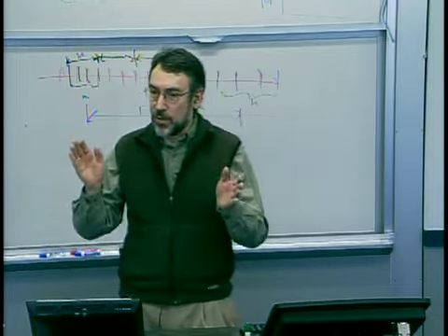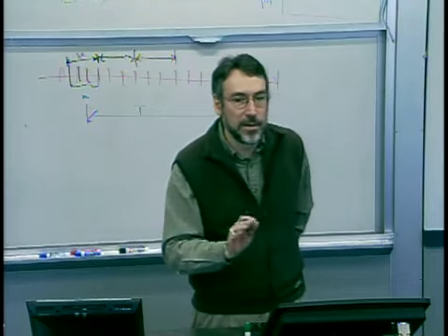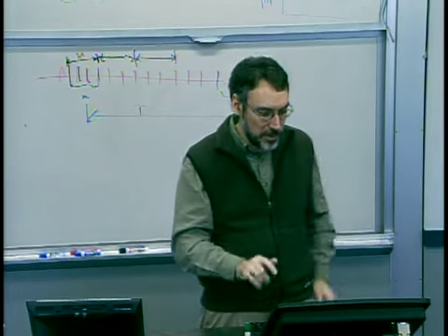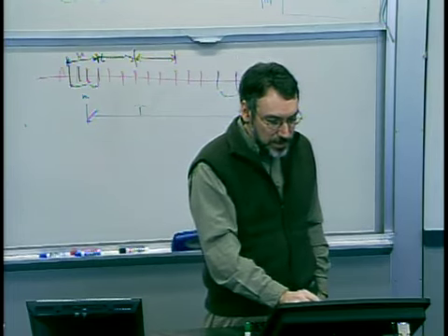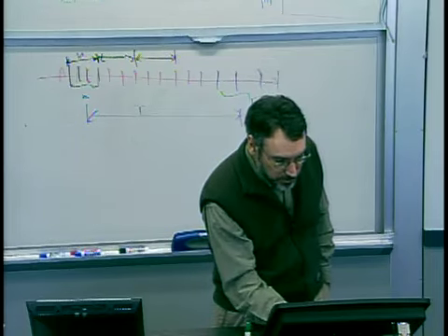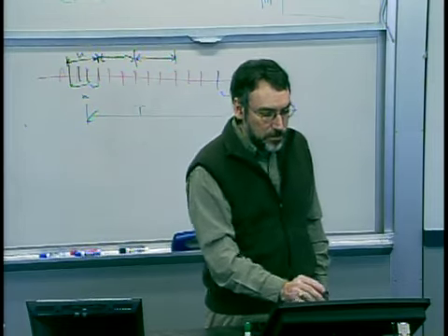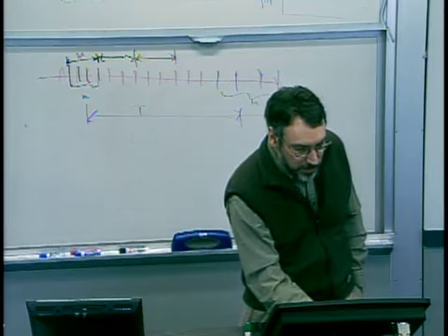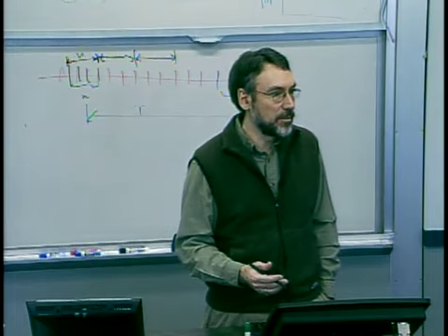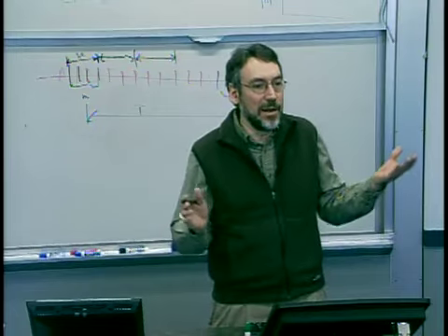And here I'm just using tolerance limits. I'm not talking quality loss at this point. CP, CPK are actually just defined for pure plus minus tolerance limits. So what's drawn here is a set of spec limits that go, these are sigma markings. So if I look at, first off, CP and CPK, my lower spec limit, upper spec limit, those are 6 sigma apart compared to the variance of my underlying process. That's just a CP of 1.